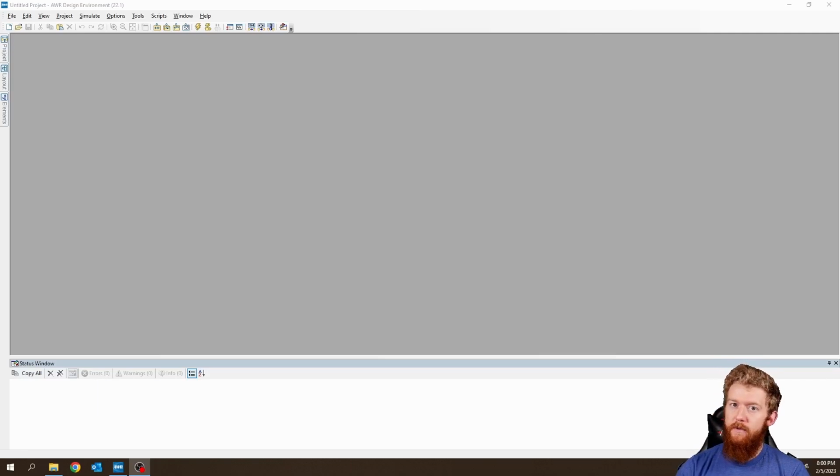So today I'm going to be going through all the topics that you're going to need to have success in the homework and in the class later on. That's going to cover just the basics of getting started with AWR. Then we're going to talk about how you can make a schematic and add text to that schematic, and then how you can start adding actual circuit elements: transmission lines, resistors, capacitors, lumped elements, things like that.